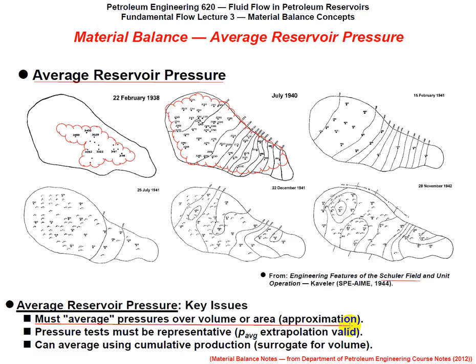So how do you get the average pressure in this field? Anybody? Santiago already said that you have to take shut-in pressures, and you can see the shut-in pressures are listed, the little numbers. But we have to take the shut-in pressures and somehow come up with an averaging formula based on volume. So we have to know the volume associated with that pressure measurement.